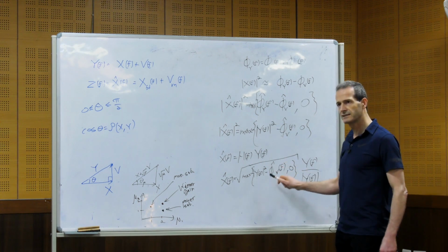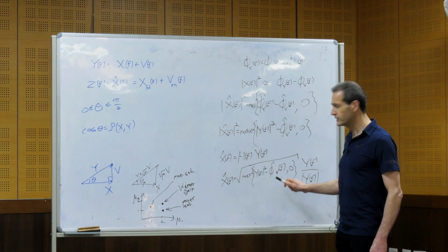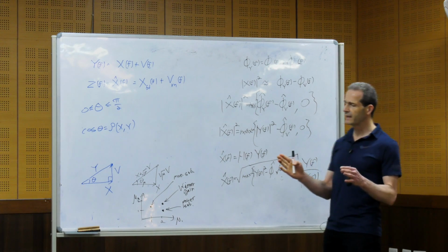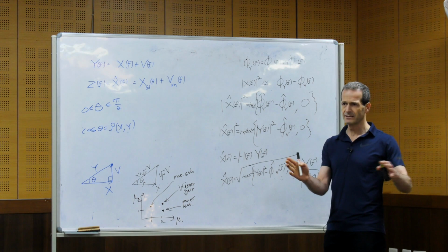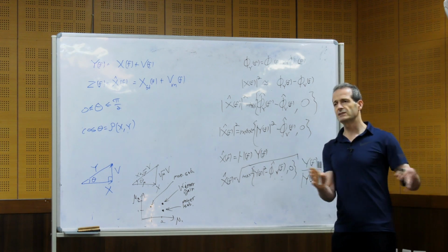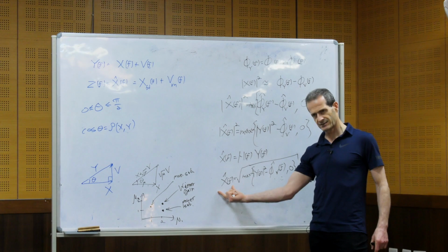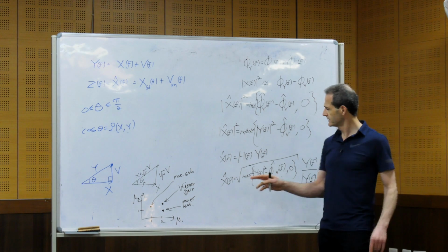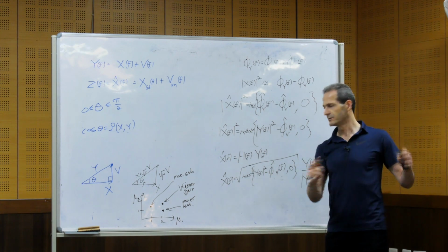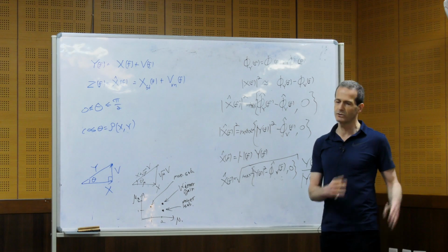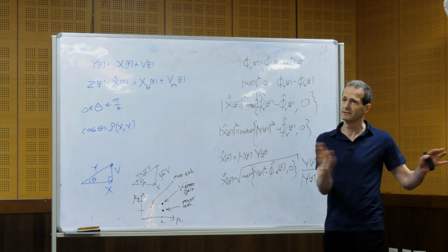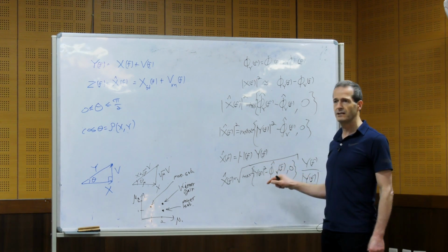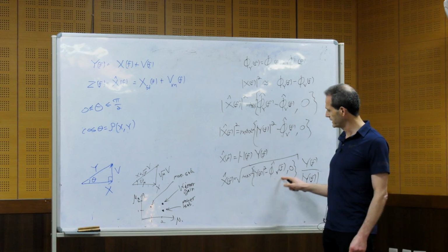The noise variance is still unknown, I said, but it's easy to estimate. Why? Many times the noise is stationary, and even if it's not stationary, you can use pauses of the signal, when you know you don't have the signal, and take the variance and average it using the noisy measurement, because the noisy measurement will contain only noise. So you can average that. Okay? So in many cases this is easy to estimate. That's why I have it here.